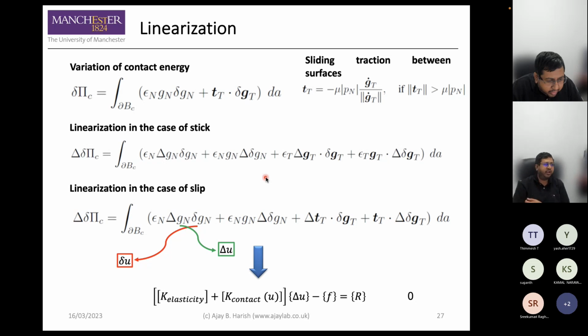When you start to neglect terms, your stiffness matrix is no longer consistent, and the convergence starts to slow down. If the residual is not correct, then we'll never get convergence. But if the residual is correct, which is easier to calculate, but our tangent stiffness is inaccurate, then we would end up with very slow convergence, though we would most likely still be able to get convergence.